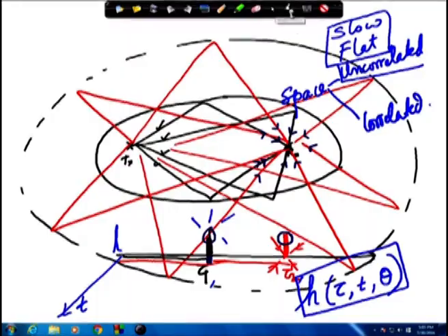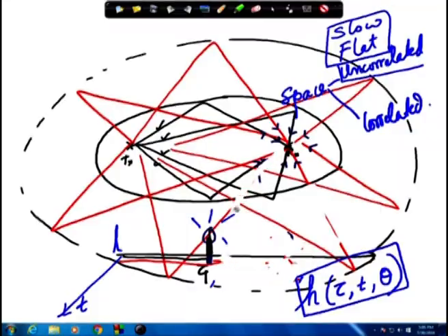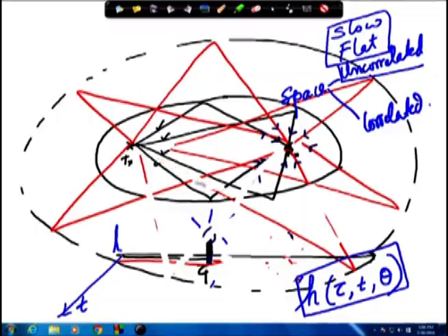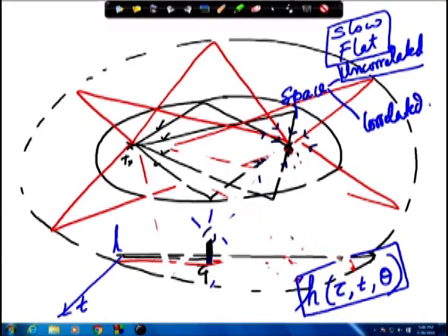We don't have the red ones, so only tau 1 is present. So all the delays, these are not present. Only the black paths are present. If you could imagine, that is the flat fading. That's just for the reminder. So only the black lines are present.